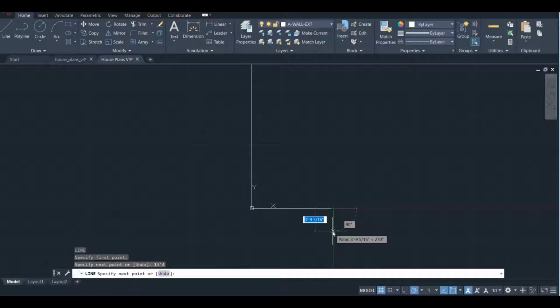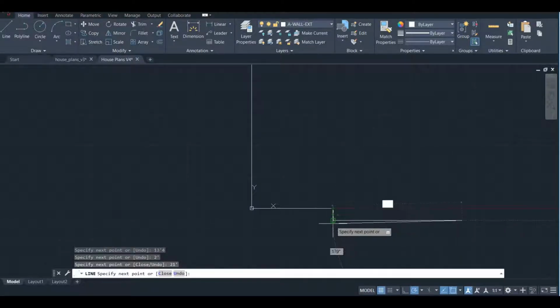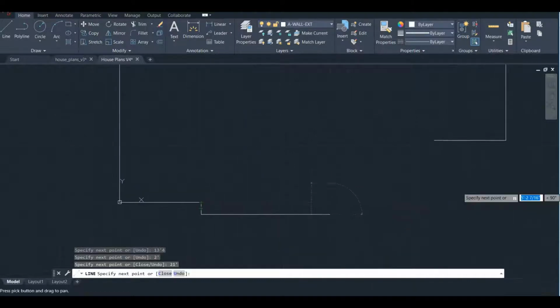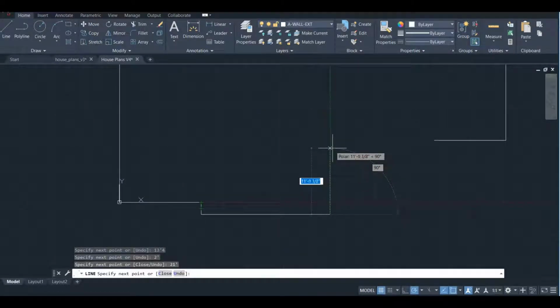Okay. 42 feet. So this little jog for the garage is something that you don't really want to do with an ICF, because ICFs are not good at making tight corners like that. You need to use 2 corner blocks, and you're going to end up cutting off a big part of the short corner to get that to fit, which is not really an efficient use of material.